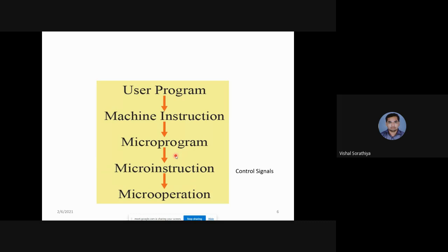So whatever instructions are written in that micro program, like if you have written XOR and there are 5 lines that execute from your micro program memory, then each and every line is fetched from the memory, and at that time a control signal is generated. The control signal gives the instruction to the entire computer that under this micro program, this many blocks first need to be on, then this many blocks need to be off, then data goes from here to there, then data goes to the complement, data goes to the end.